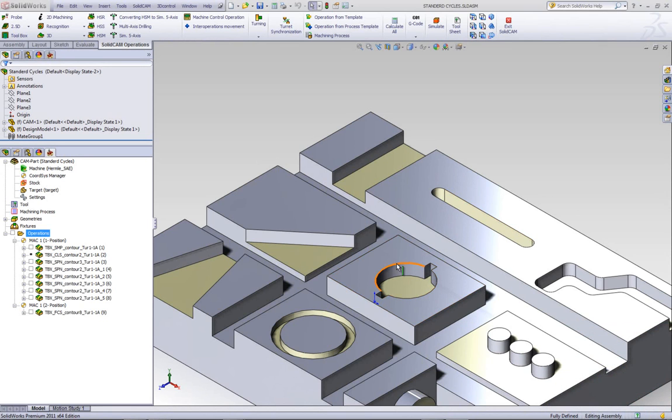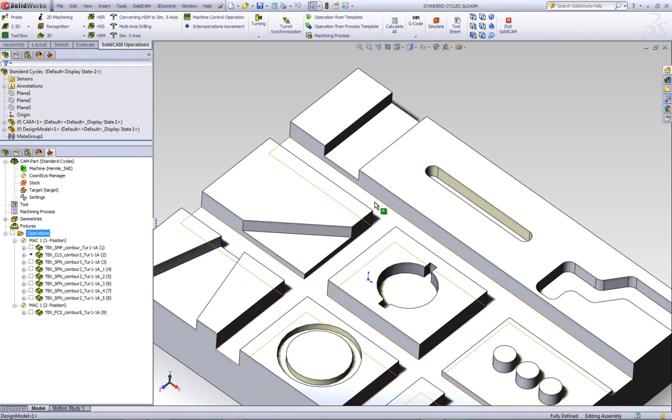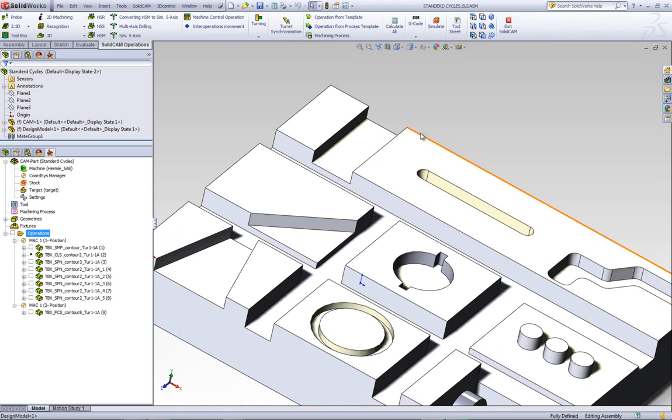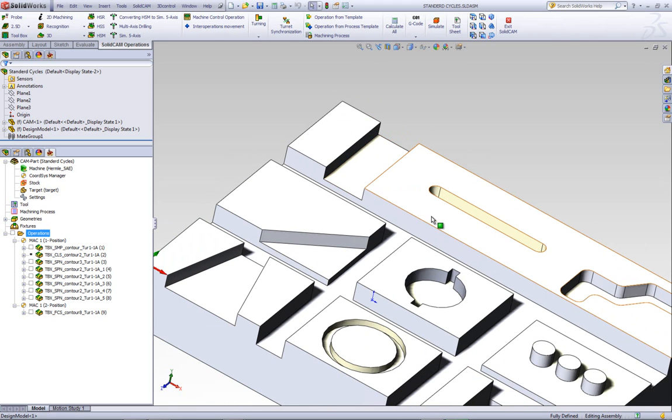What exactly is Toolbox? Toolbox is a series of canned shapes that we can actually program just the geometry, and the actual toolpath is automatically calculated by the program itself. All we have to give is geometry, the tool itself, and the depth. The big advantage of this is that you have all those parameters that we used to put in that you do not have to put in anymore, because they're automatically figured out according to the type of shape that we will be machining. Let's take a look at the toolbox itself.